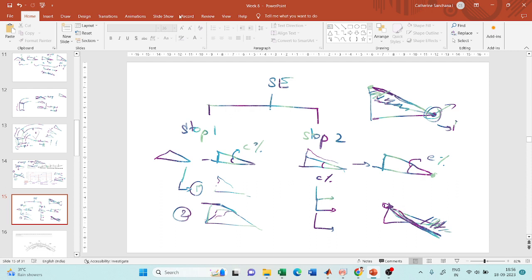Or you can do it in another way, where you can rotate it about the center. If this is my C%, I can keep this point constant and rotate it like this, which means I will add some material here to increase the height of this, and I have to remove some material here to decrease the height of this.